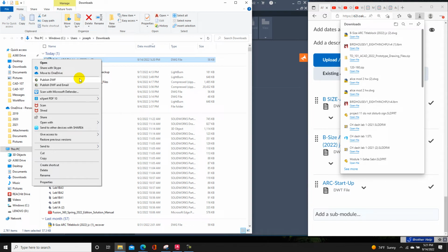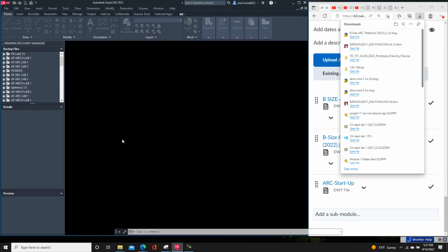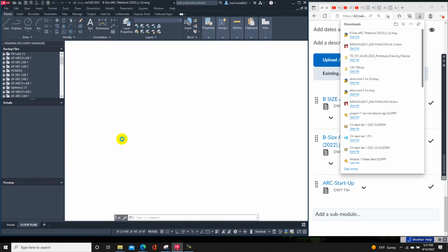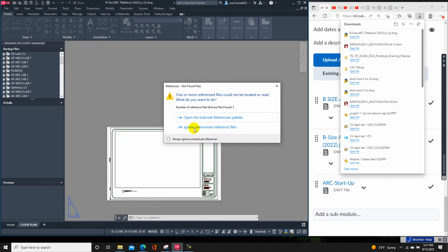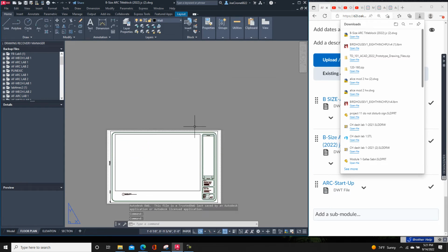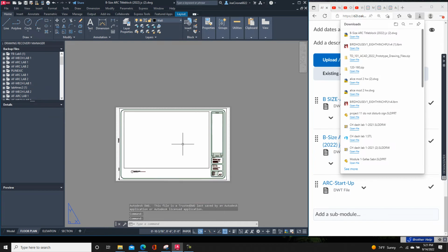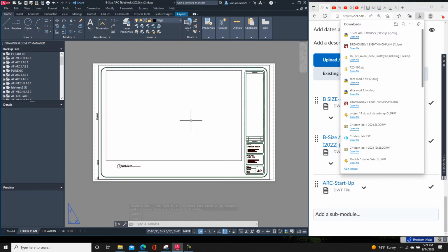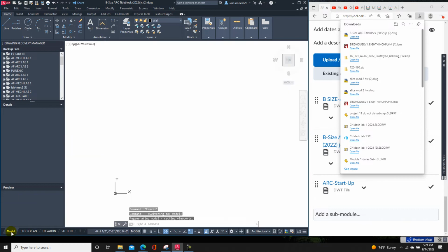I'm going to open that with AutoCAD 2022 rather. I think it's 23. And this just gives me a frame to work on within my drawings. Remember that paper space has this little right triangle in the lower left-hand corner. It's basically a frame for our drawing. And then this is a viewport that will display whatever we draw in model space.